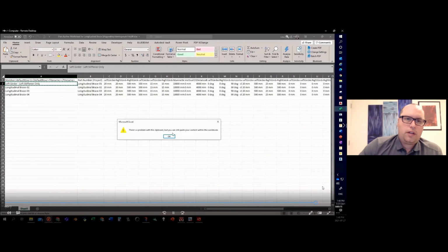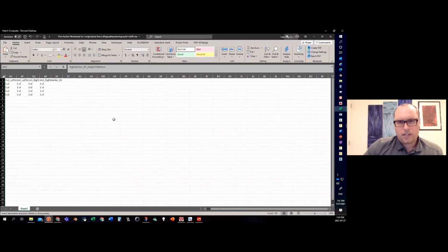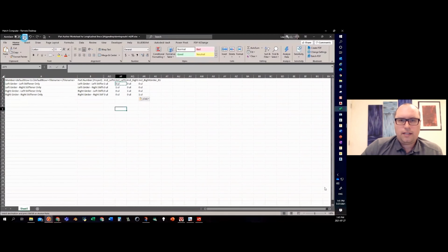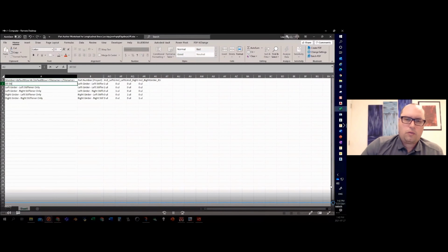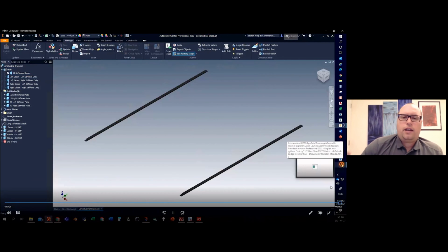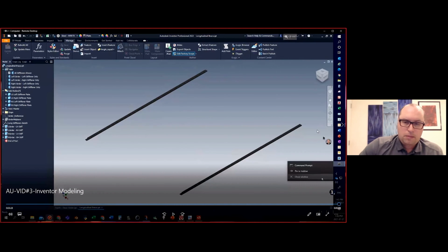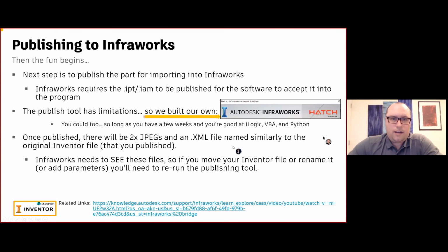As well, within Inventor, you can easily put things into a spreadsheet format and then adjust the variations of things in that spreadsheet. So in this instance, I have the option to turn the left or the right or just individual stiffeners on as I need to. And then I can create any other variations of that, and then it's all published. So that was quick, but again, you guys can slow that down as you need to.